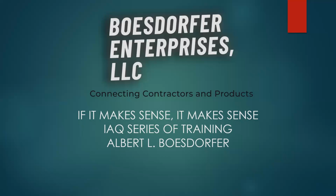pertains to an issue that I had on a building, but it wasn't this exact same equipment. So this was kind of built from scratch on the scenario that if you have this issue with 100% outside air, in other words, a negative pressure building, you got to get that building back to a very slight pressure, which is basically 0.001 inches of static, or about introducing about 2% of the required building volume back into it to positive pressurize it.